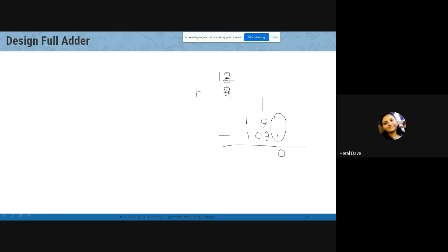So this is the limitation of half adder. So in real life, generally designers use full adder, because full adder is having 3 input terminals and 2 output terminals. This is a limitation of half adder. Half adder can add only 2 bits. But whenever carry is generated and it is forwarded to next bit, the answer will be wrong if we are using half adder, because it is having only 2 input terminals. Where should this one be connected? So we should have full adder.